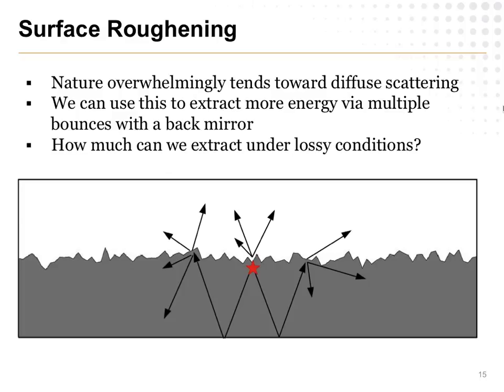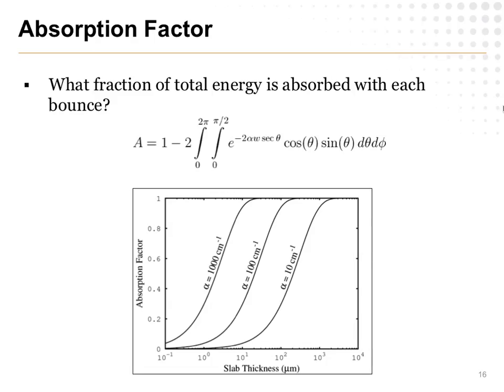Although I have been told if a photon gets reabsorbed in that p-n junction in just the right way, it can actually re-excite an electron-hole pair, which will then wander around and recombine and create yet another photon, and I believe people have dabbled in that to try and make their LEDs more efficient. The idea is instead of losing that energy to heat, you're creating a new opportunity to re-radiate a photon and get it back out again. I don't know how successful that's been, but I do know that idea is on people's minds, and they've dabbled with it in the literature.